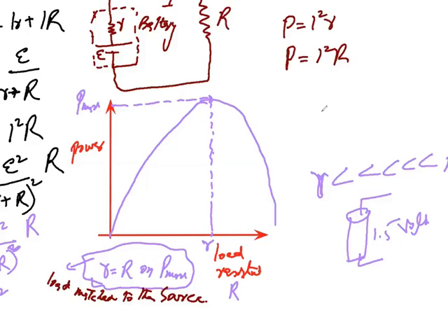But if you get this condition, your internal resistance is equal to this, then you will get a maximum power. Then it means practically this resistor will be very much smaller. Normally in practice this resistor has a smaller value. If you want to equalize this resistor with this capital resistor, then it will have a smaller value. So this value here is the internal resistance. That's why I represent it by small r. But the x-axis is the load resistance.